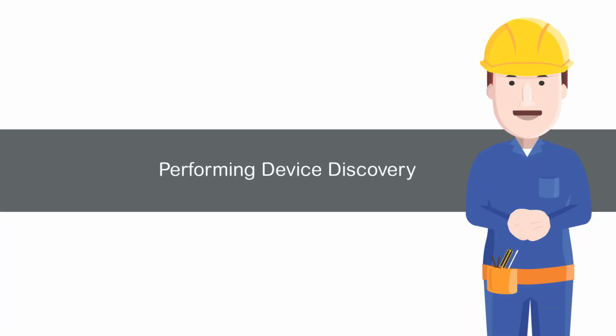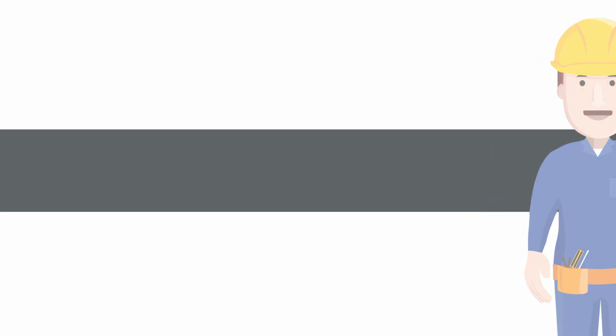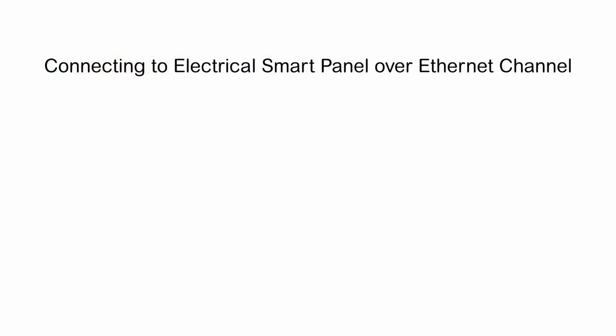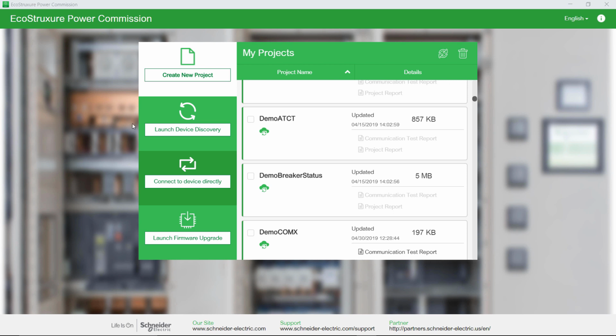My first objective is to start device discovery in EcoStruxure Power Commission. I need to set up the smart devices as per the client request, to connect EcoStruxure Power Commission to the electrical smart panel over an Ethernet channel. The prerequisite is that the software and the electrical smart panel should be on the same LAN or must be connected one-to-one. From the home page, select Launch Device Discovery.